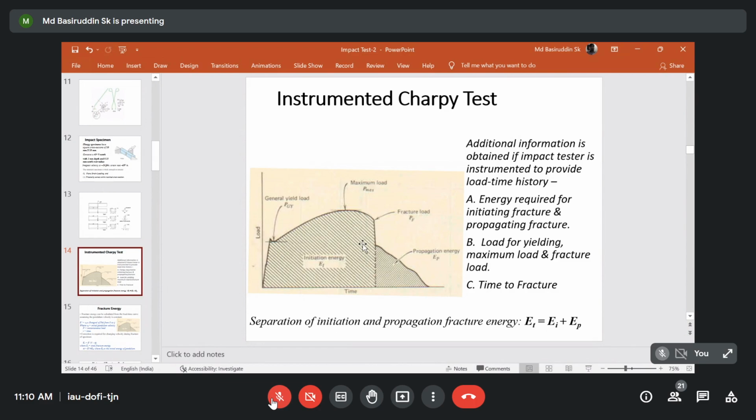Now you need to think that this sort of curve is for particular temperature conditions, like the curves you find when you do the test at high temperature. If you do the test at high temperature, it is not that you will always get a complete brittle fracture. You will find a mixed kind of fracture, or even ductile fracture. But yes, fractures will happen.